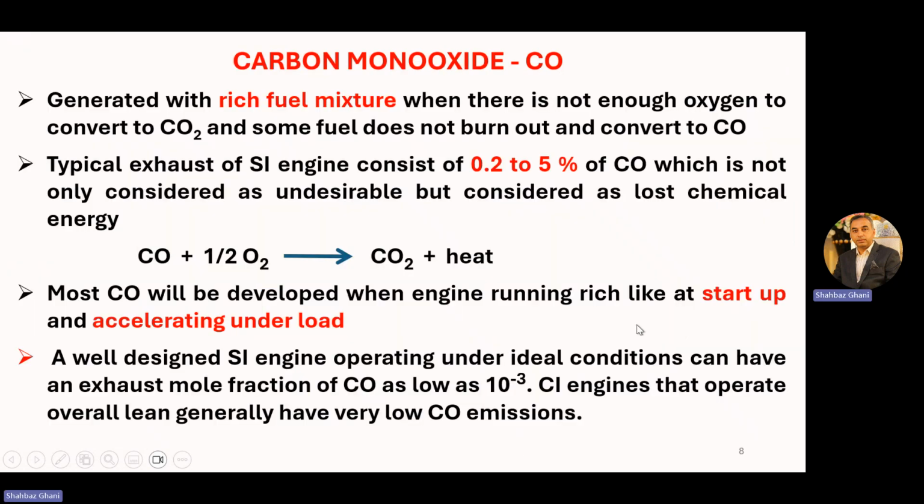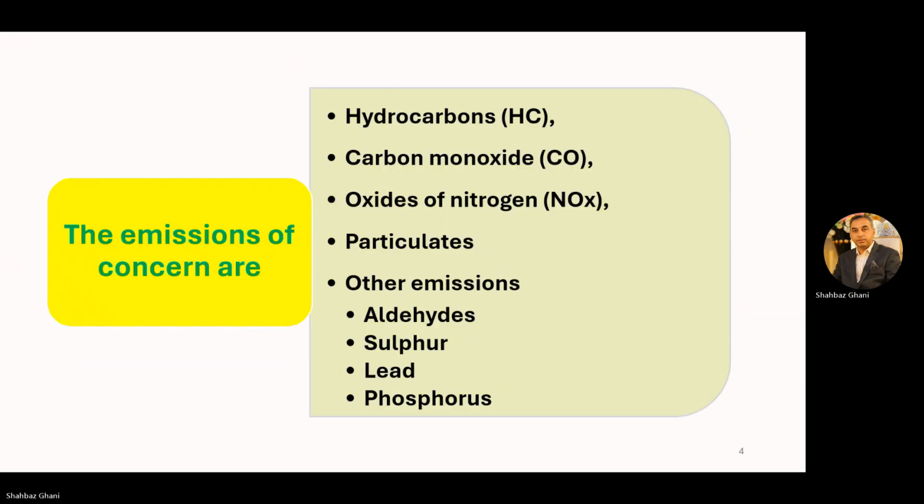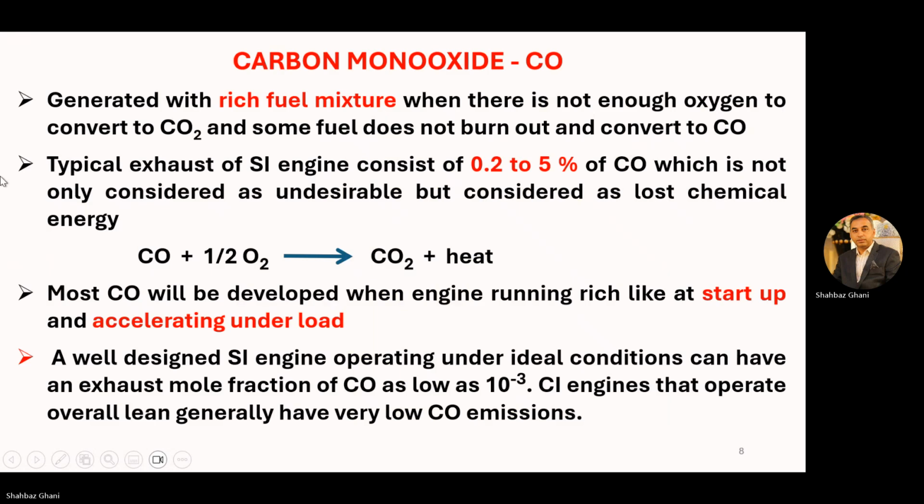Now, the second part of the causes, high carbon monoxide. Carbon monoxide is generated with a rich fuel mixture when there is not enough oxygen to convert to carbon dioxide, and some fuel does not burn out and converts to carbon monoxide. When we have less oxygen, the end result will be carbon monoxide. If we have abundant oxygen, then there will be no carbon monoxide, simple. But a rich air-fuel mixture, with less oxygen, results in carbon monoxide.